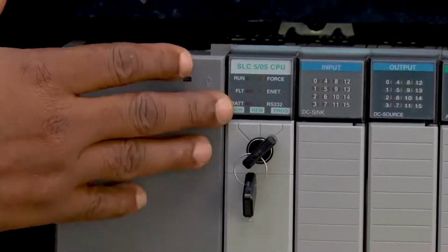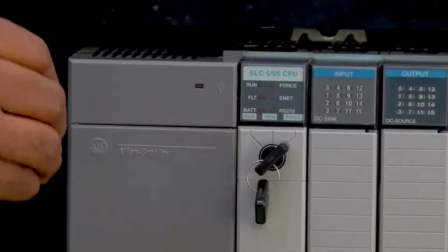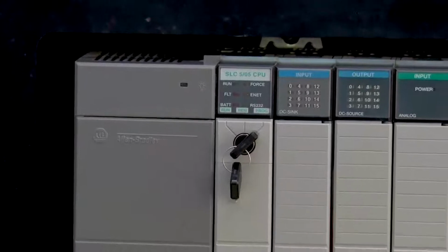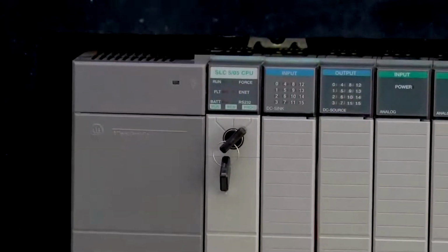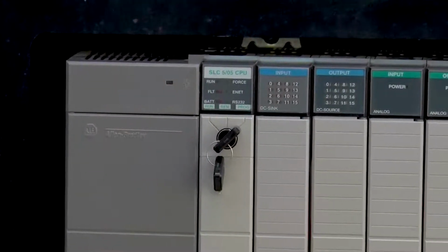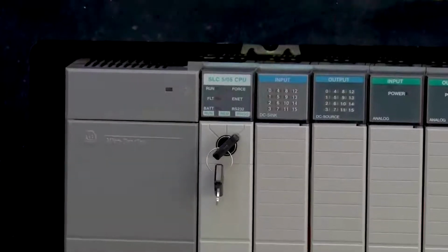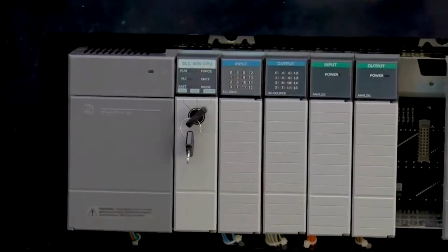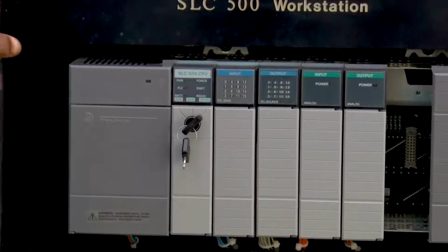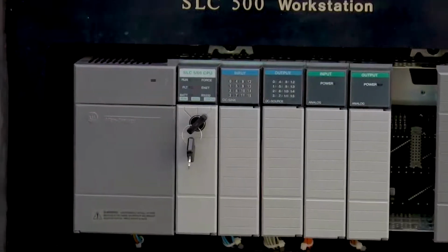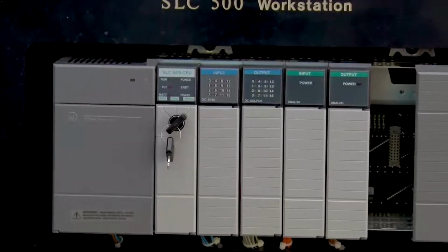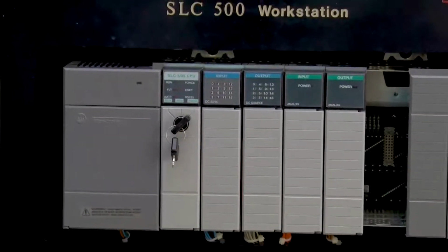Another terminology that is used here in the PLC is, when you want to send information from your laptop, that's the programmer, or the PG, to the PLC, use the word download. Not upload. Download. That's the PLC terminology. And when you want to extract information from the memory of the PLC, you upload to the programmer. So this is very important. By the time you begin to write programs, you may use the same internet terminology, trying to upload a file or download a file from the net.